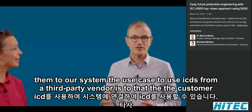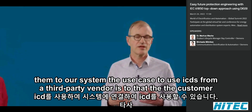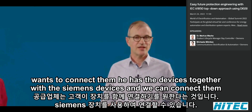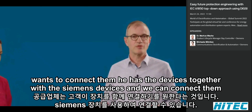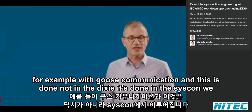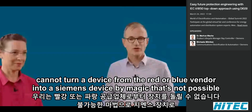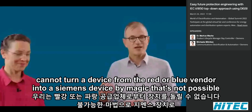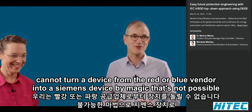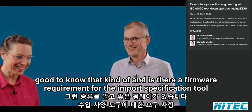The use case for ICDs from a third-party vendor is that the customer wants to connect them. He has the devices together with the Siemens devices, and we can connect them, for example, with GOOSE communication. And this is not done in the DIGSI, it's done in the Syscon. We cannot turn a device from the red or blue vendor into a Siemens device by magic. That's not possible. Good to know that, kind of.